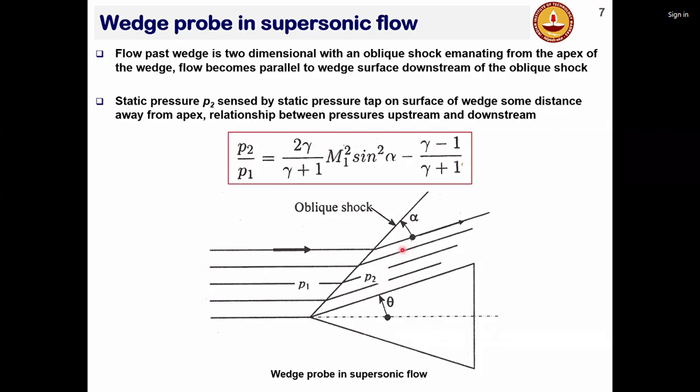So if you create an opening, there is no flow in this direction, but the shear that is happening closer to the boundary would give rise to some kind of pressure, that is static pressure. The same can happen for the stagnation region P1. So if you know P2 and if you know P1, then you can predict what is the Mach number M1, from that formula.